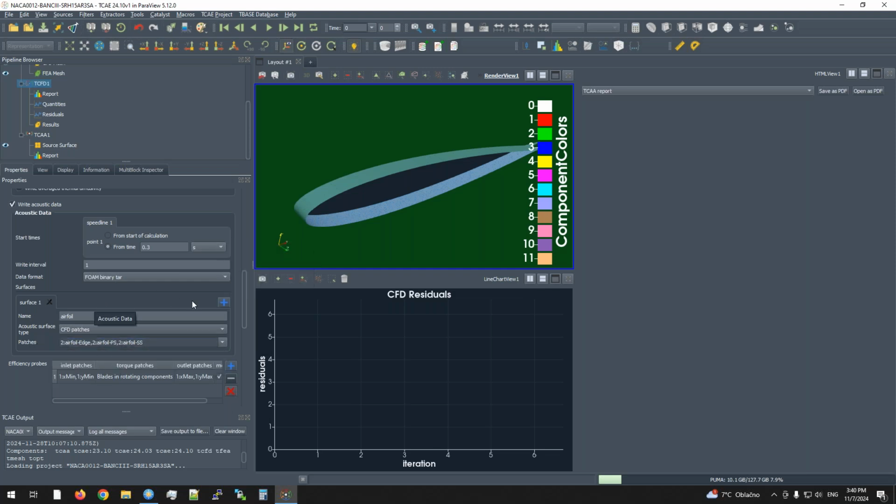And now the new feature is that you can even add, there are two new features basically, two in one, that you can add more surfaces, more acoustic surfaces, which is really important because typically for acoustic simulation, the CFD simulation takes a lot of time. It's simulation for weeks, depending of course on the case and the mesh resolution, but it's really demanding. And so you would like to store as much data as possible for the later acoustic analogy, because then you store the data, and you can make the analogies from different surfaces and play around.